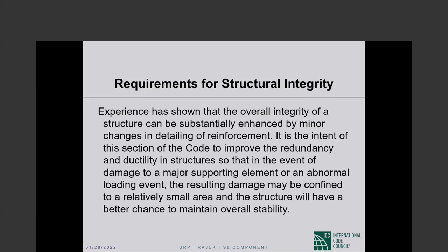BNBC, I don't know exactly where it is, but in IBC, there are detailed pile detailing requirements. And some things are relaxed, like everything that applies to a column doesn't apply to a pile. But the spacing limitations, I believe, are the same. So this will be my answer unless I find something else in that chapter. I would like to check. Okay.